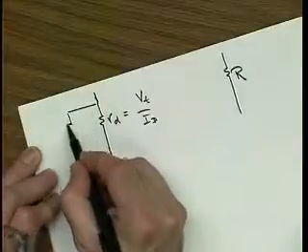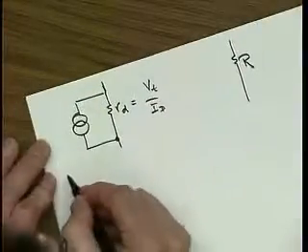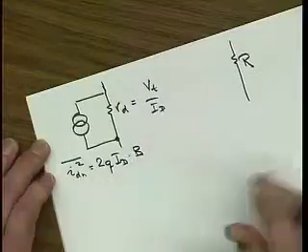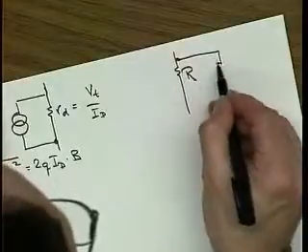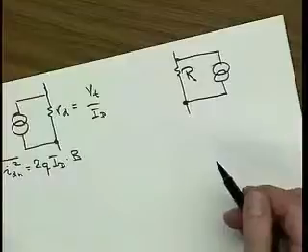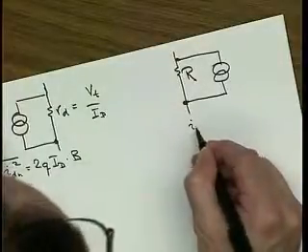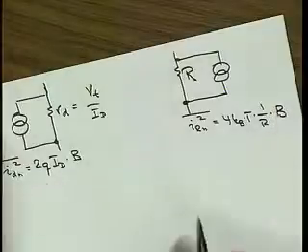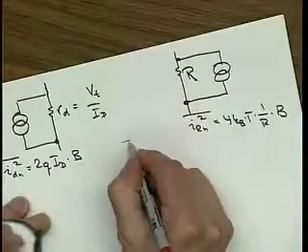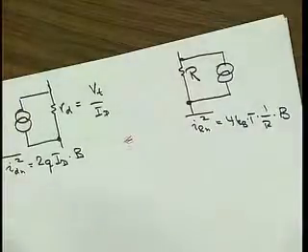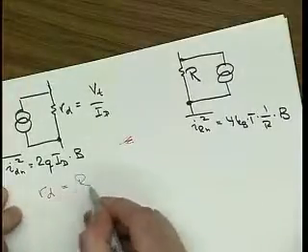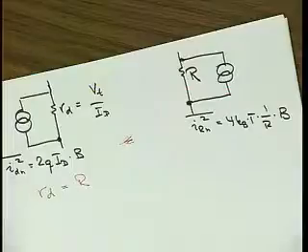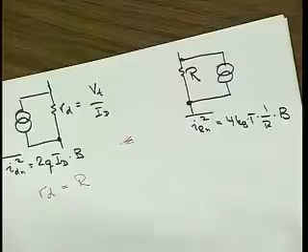Now here, in parallel we have our noise current source, and the noise current is going to be IDN squared equal to 2q times ID times B. And here we also have, using noise current, IRN squared equal to 4 kB times T times 1 over R times B. Let's set RD equals R. Let's suppose that we are in a situation where we just need a resistor of a certain value, and we want to decide, should we rather use a diode or should we use a real resistor to make that resistor?